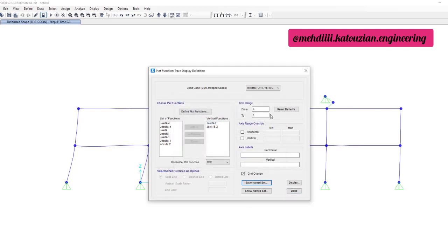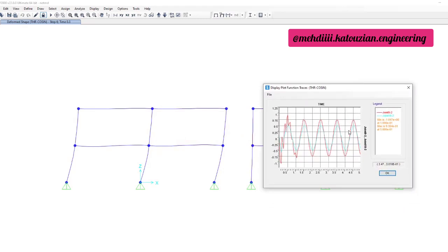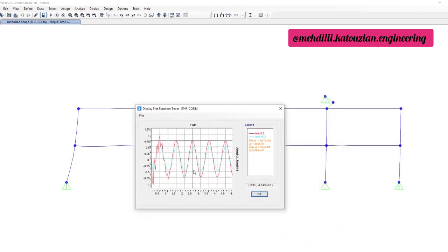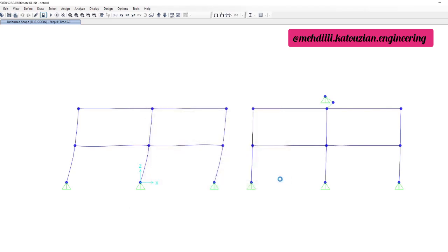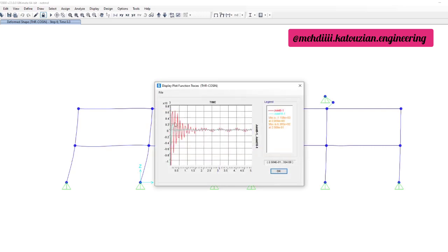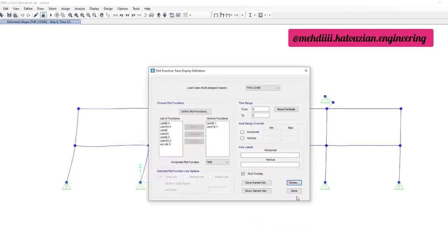Okay, and let's see the cosine function, which is the same displacement. Yeah, here it is. The same changes are made for cosine, since the TMD displacement is less, maybe 30% less. And we can also see the acceleration. This too is acceleration. Yes, quite interesting. It's about 50 or 60% reduced structure vibration. There is some discussion on this part, but I'm not going there, because the lower-rise structure has some sensitivity to the short period.